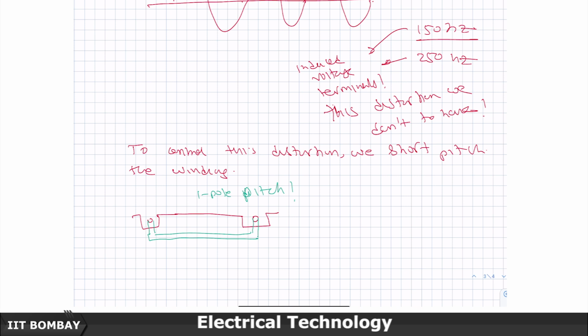So, when we join them in series, their EMFs are exactly in phase and they add, so if there are n turns in this particular slot, you will get that much addition. Then the next slot comes here and the next slot comes here, and that EMF is slightly displaced by that angle alpha which we talked of in the last class, and then the next voltage comes like this, and we did this netting last time considering this phase distribution and came up with the distribution.